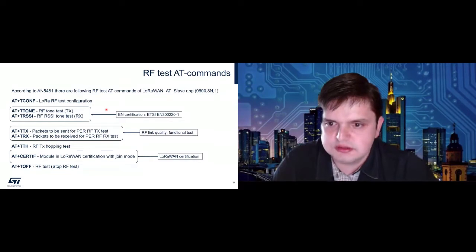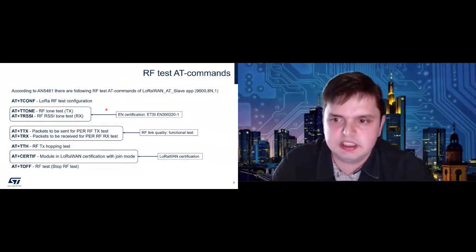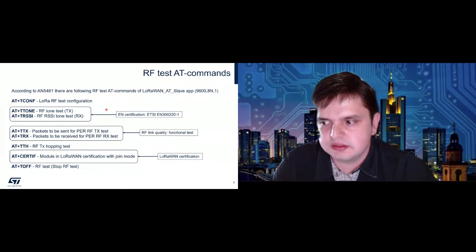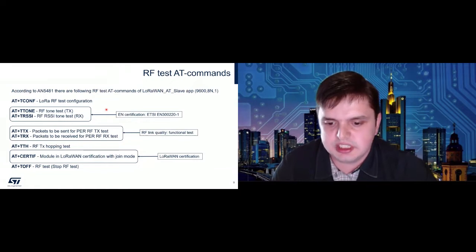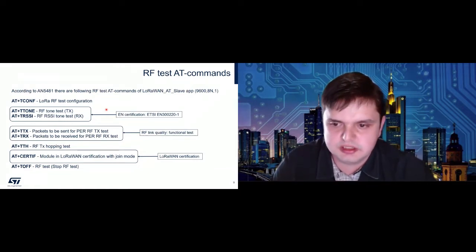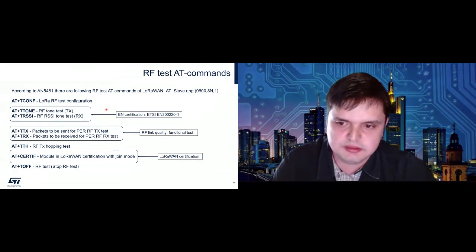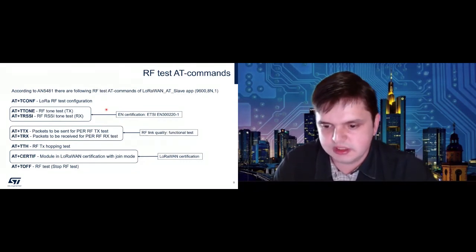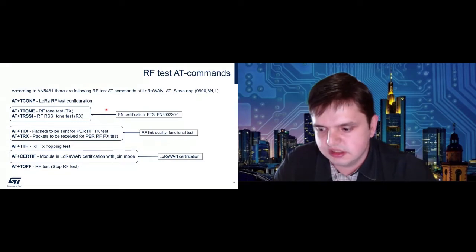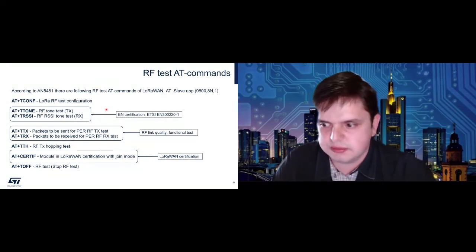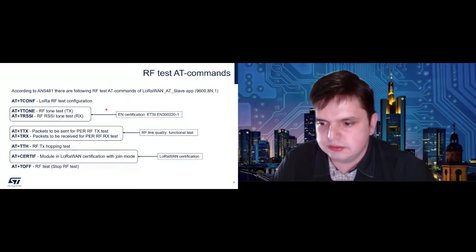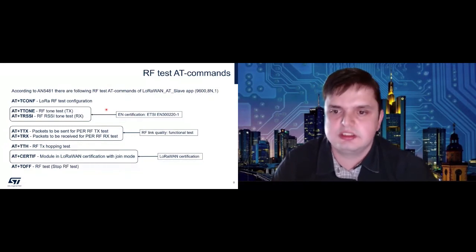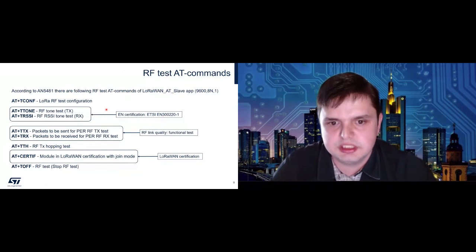I would also mention in this case our RF lab in Prague, because not only do you need to battle it yourself, we can also help you. And we have a nice RF lab in Prague, but for that, it is really important to leave at least one UART, meaning both RX and TX, on your PCB, at least as a test point, so that the AT slave can be loaded during the development, and you or my colleagues from the RF lab can perform the tests.